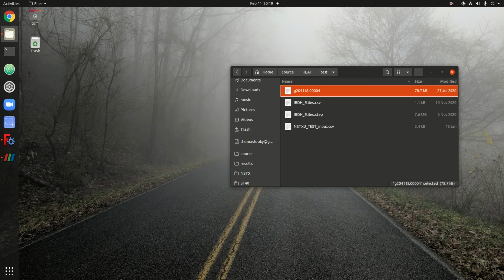For today I'm just going to be using this G file, which came from the tarball for the test run, which is available on the GitHub page. And there's a whole video about how to download the AppImage and download the test run case. So if you haven't seen those videos and you haven't downloaded them, go watch those before you do this video. But basically, I need an EFIT and I need a point that I want to launch from. So I got the EFIT. This is the GEQDSK, which is a magnetic equilibrium reconstruction in EFIT.